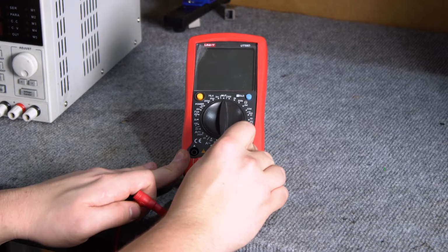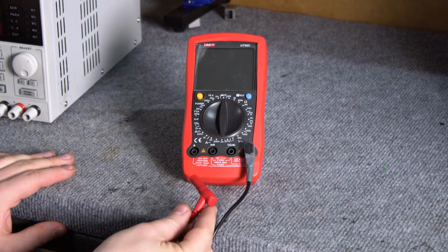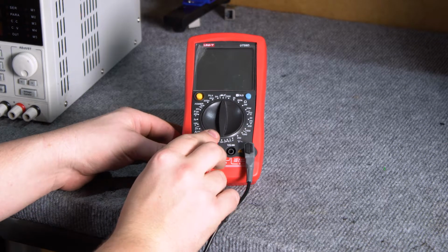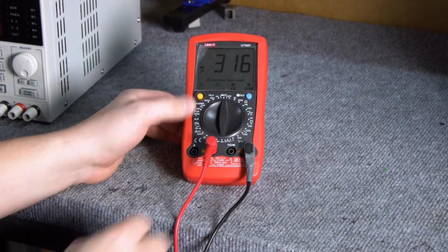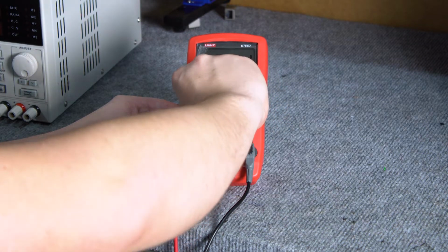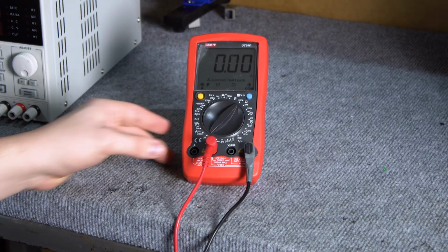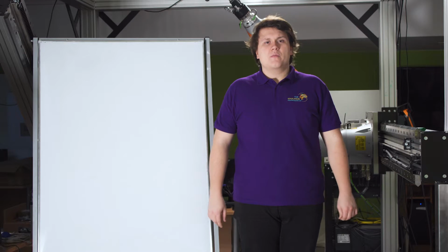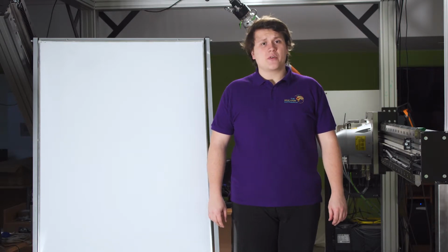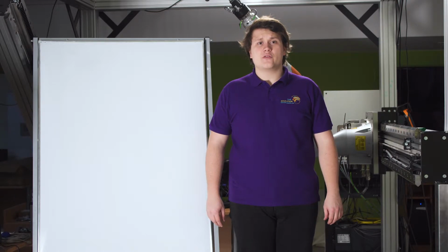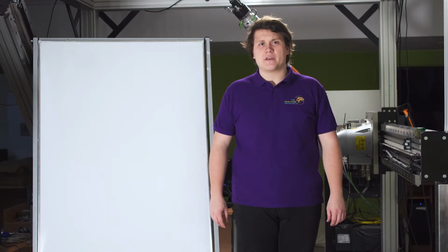Analogously to switching on the probes, which we plug into the COM and A or mA terminal, on the opposite side we will see a minus sign with direct current and the same value with the alternating one. Previously, we told you how important it is to connect ammeters properly and to know which terminals we are using. Connecting an ammeter in parallel may result in a short circuit and a very big current flowing through it that can damage our system.